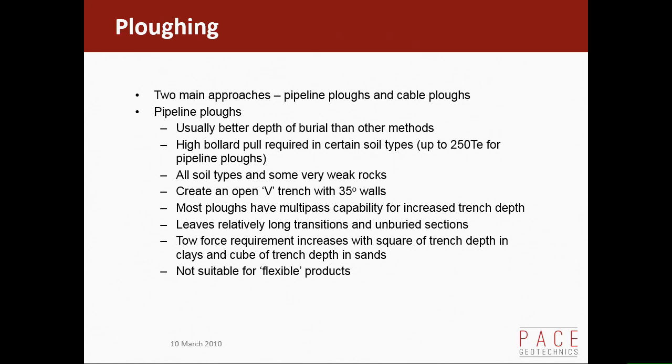In America they trench all pipelines to about 60 metres water depth, and then they don't really bother so much after that. However, if the requirement is for thermal insulation of the pipeline, then I've seen jobs trenched down to about 1,000 metres water depth.